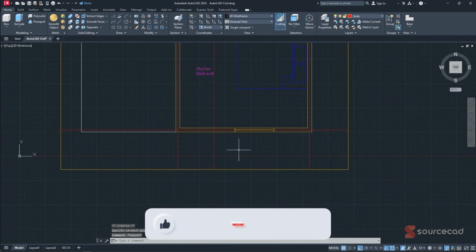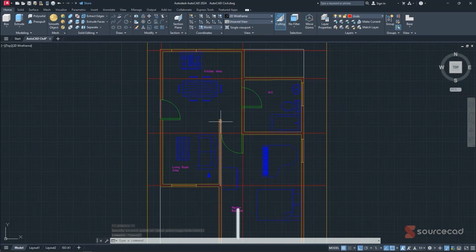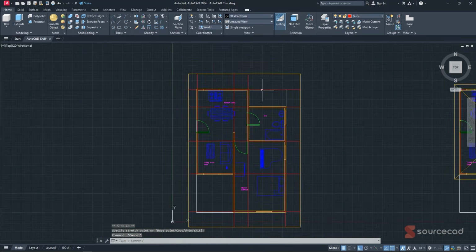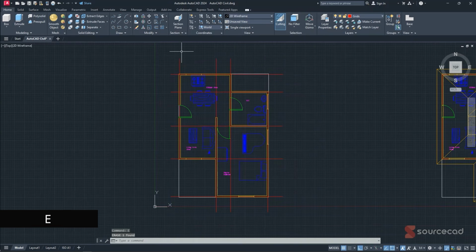So that's the way we actually place our grid lines. Very easy. The same with this line here. So click on this point or that node and extend it up to that point. And once you're content, once you see that all your lines are now touching this, you can simply select it, E for erase, and just like that, now it's gone.